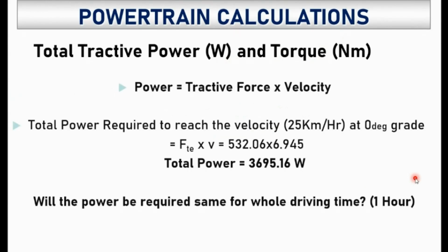With that, now when we wanted to calculate the power, power is velocity times force, or force times velocity. With that, we know we can calculate the total power. At least for this case, maybe we did some calculation, and maybe the total power that is required comes up around 3 kilowatt based on all the assumptions that we had, vehicle weight considered, and so on. So this is what we had.